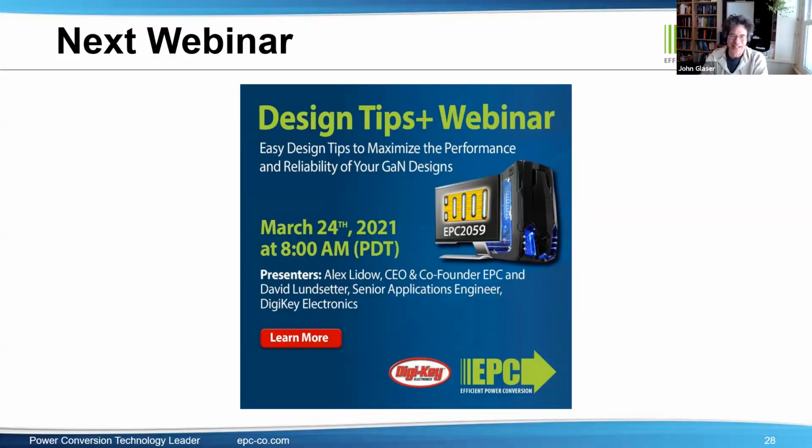It's certainly true, right? The faster the edges you have, the easier it is to couple to the outside world, the smaller structures you have. But at the same time, everything we do to minimize inductance is basically shrinking that power loop. And the smaller that power loop is, the less effectively it couples to the outside world. Inductance is basically all that energy that you don't want stored outside the actual structure.